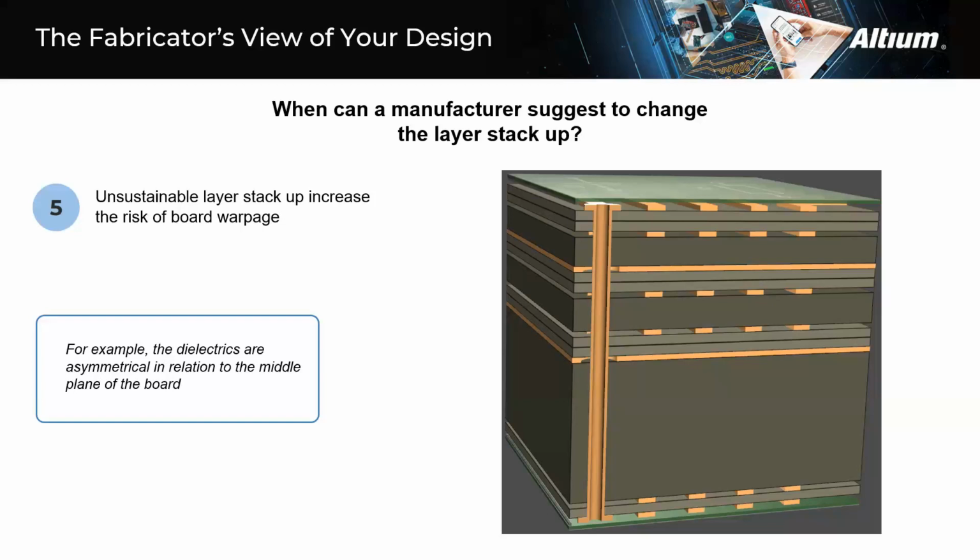However, there are instances where an asymmetrical layer stack-up is feasible. For example, when heterogeneous materials are used, such as plain fiberglass combined with high frequency materials like Rogers. Additionally, sometimes inner layers are heat dissipated by copper with increased thickness. These are special cases which should be considered and analyzed accordingly.